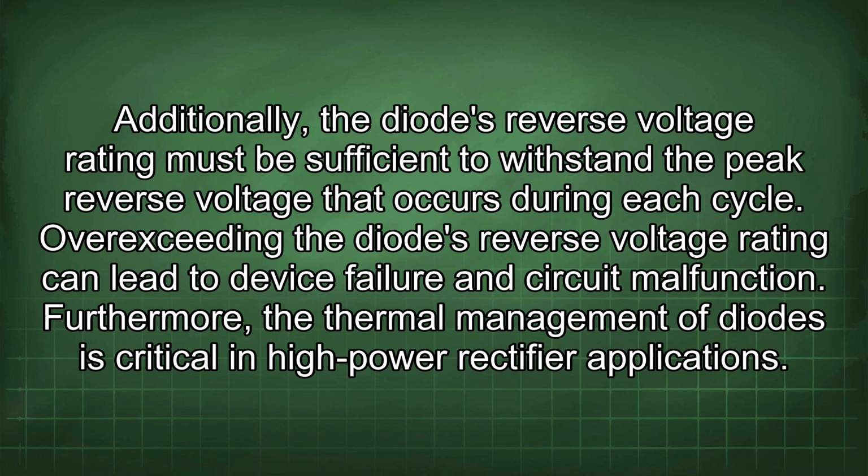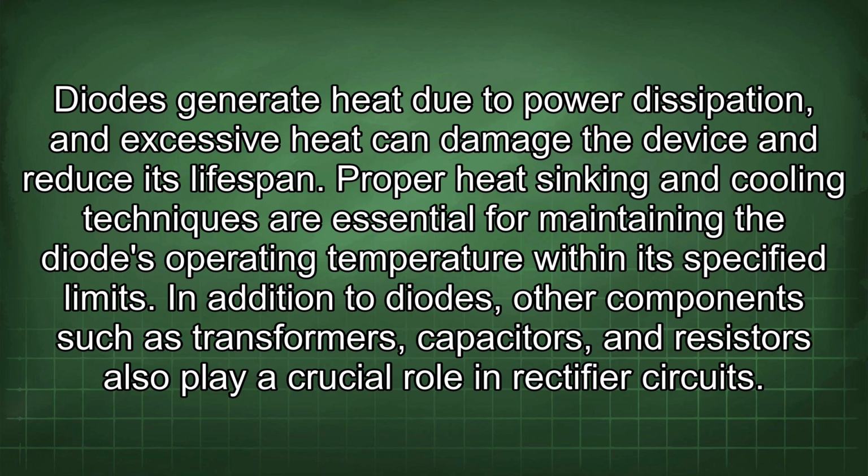Furthermore, the thermal management of diodes is critical in high-power rectifier applications. Diodes generate heat due to power dissipation, and excessive heat can damage the device and reduce its lifespan. Proper heat sinking and cooling techniques are essential for maintaining the diode's operating temperature within its specified limits.